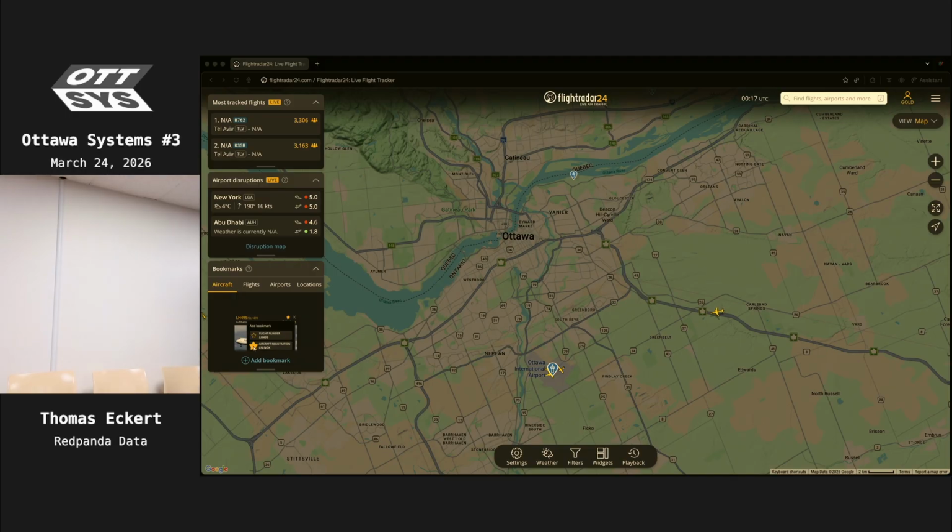Yeah. So it's because of the higher frequency. You want to tune to 1/4 of the wavelength, and that's where you're going to get the best signal. And higher frequency, so I want to tune. This is a 7 centimeter antenna.